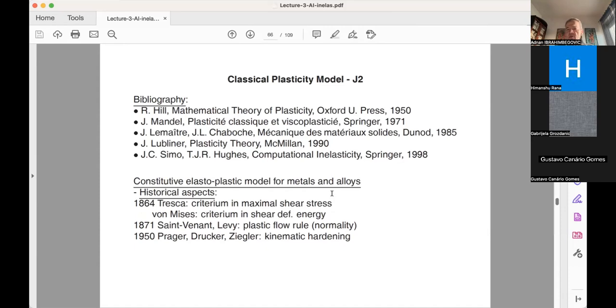In other words, you have three different values of principal shear stress. This could be simply computed as the difference of principal axial stresses. Let's say the principal shear stress 1 is (sigma 1 minus sigma 2) divided by 2, (sigma 2 minus sigma 3) divided by 2 is the second, and so on and so forth. So basically, these are like three different surfaces. That's why you call it multi-surface. And for computation, sometimes, you know, people before didn't figure out what to do with it,